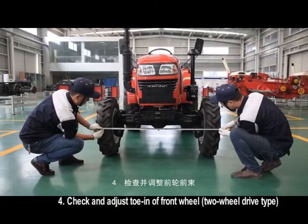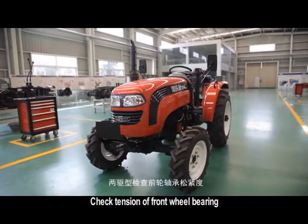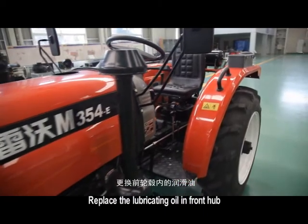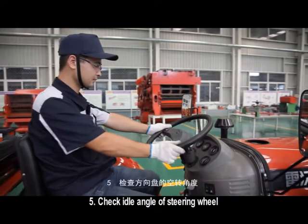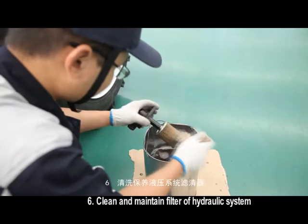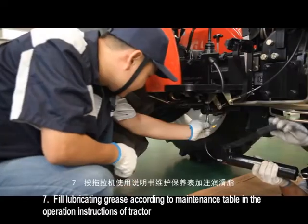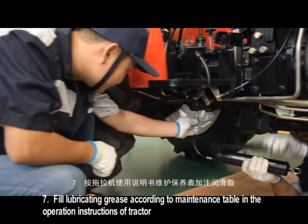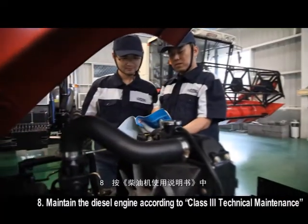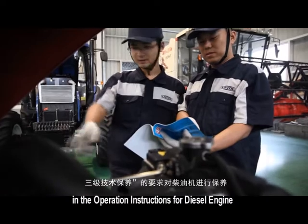4. Check and adjust toe-in of the front wheel, 2-wheel drive type. Check tension of the front wheel bearing. Adjust if necessary. Replace the lubricating oil in the front hub. 5. Check idle angle of the steering wheel. Adjust if necessary. 6. Clean and maintain the filter of the hydraulic system. 7. Fill lubricating grease according to the maintenance table in the operation instructions of the tractor. 8. Maintain the diesel engine according to Class III technical maintenance in the operation instructions for the diesel engine.